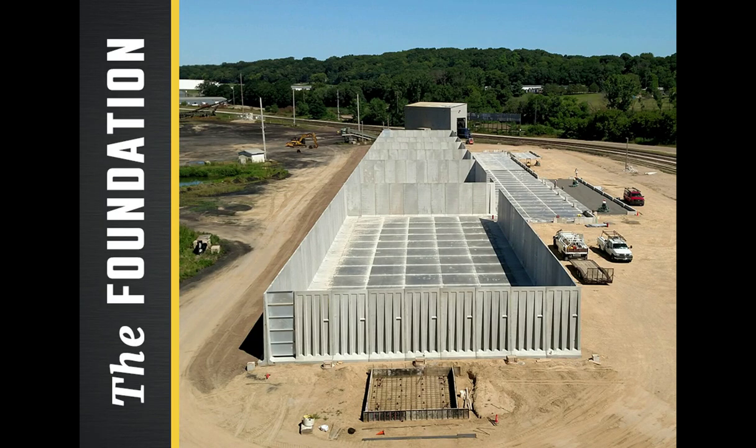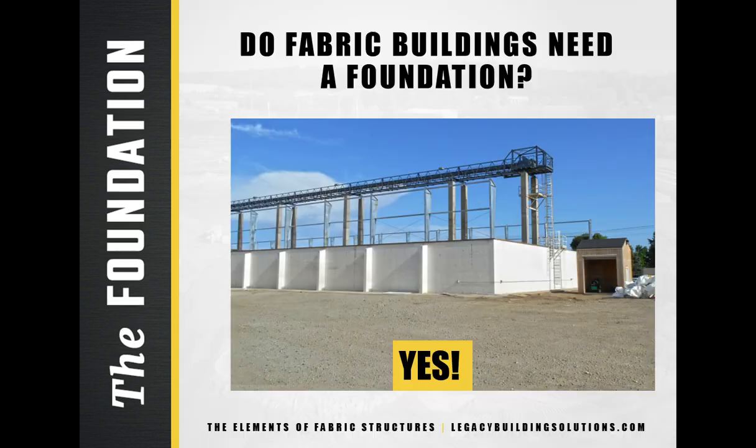All buildings that will be in place for more than a few weeks are considered permanent and require a foundation. Reputable fabric structure manufacturers will be upfront about the need for a foundation and supply options starting at the first consultation. The earliest fabric buildings were temporary tents using temporary foundations such as ground stakes. However, these foundations are not a viable solution for permanent structures.